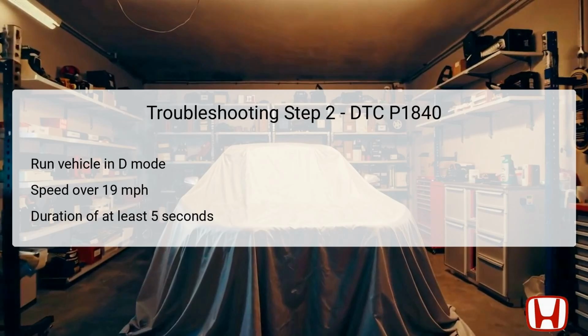Monitoring the performance during this time is crucial. Be attentive to any irregularities in engine speed or transmission behavior. Completing this step will help reveal whether there is an issue with the CVT speed sensor or with the TCM.